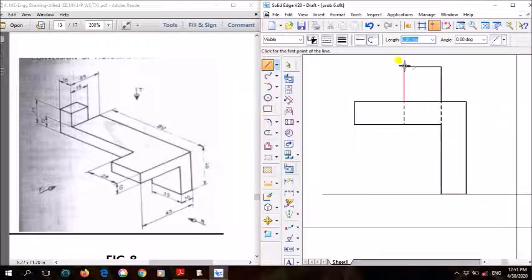So here this full it is 25, from here to here it is 25, as per the drawing. But whatever dotted line we have drawn, why have we drawn it? Because below this only this surface is upward, right? And whatever the 10 mm is there, it is behind this solid, which cannot be visible when you see it from the right side. Hence that remaining 10 mm we have drawn using what? Dotted line. Clear?